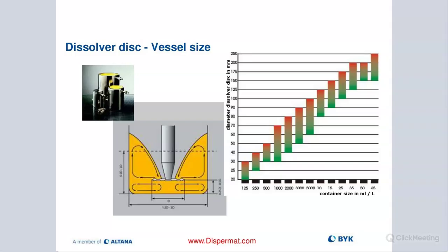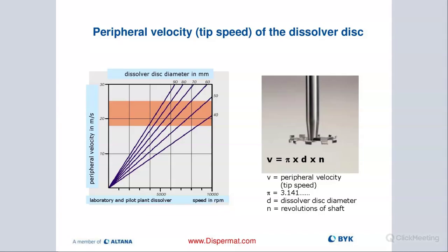if we have an optimum viscosity, to really get a good looking donut and put in the right amount of energy to pre-disperse our material. On our newer Dispermat models, the tip speed is displayed on the graphical interface. The only thing you have to do is enter the right diameter of the dispersion blade, milling disc or rotor that you would be using, and it automatically calculates the tip speed for you. So you no longer need to do it manually.